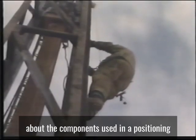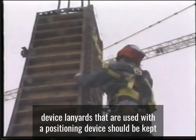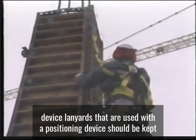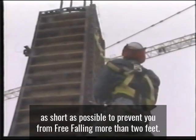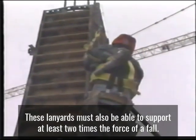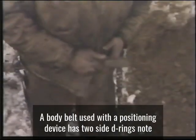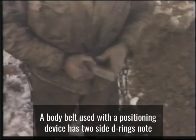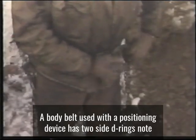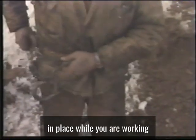Here are a few points about the components used in a positioning device. Lanyards that are used with a positioning device should be kept as short as possible to prevent you from free falling more than 2 feet. These lanyards must also be able to support at least 2 times the force of a fall. A body belt used with a positioning device has 2 side D-rings.